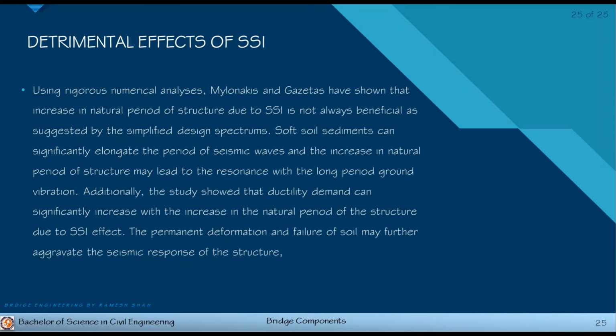Additionally, studies have shown that ductility demands can significantly increase with the increase in the natural period of the structure due to the SSI effect. The permanent deformation and failure of soil may further aggravate the seismic response of the structure.